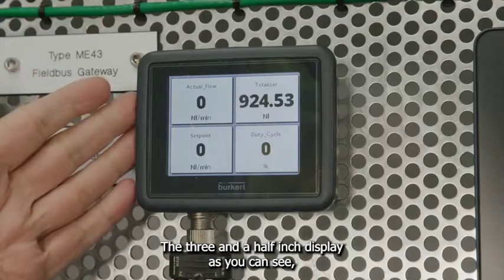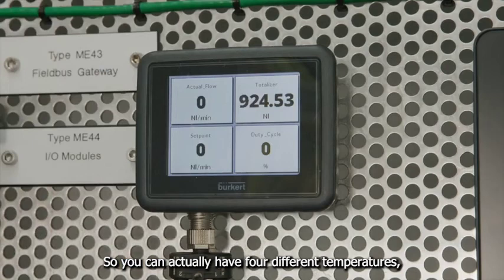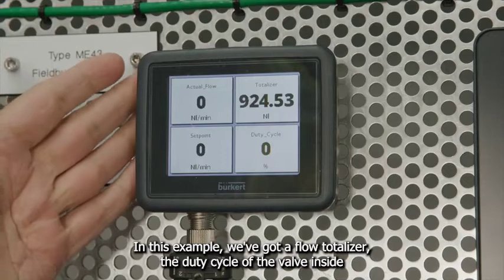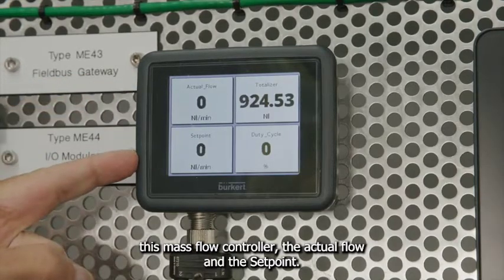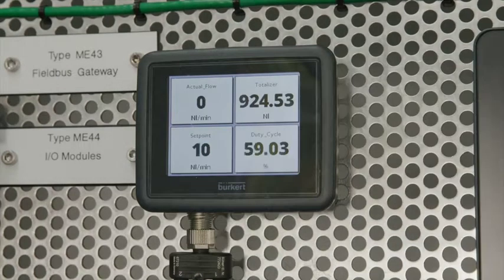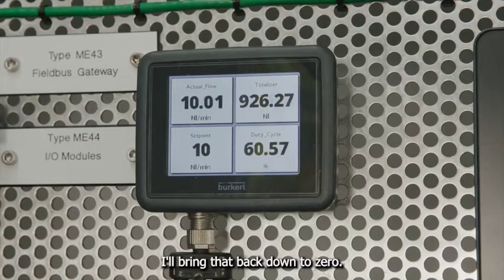The 3.5-inch display, as you can see, is a full color display and also will display up to 4 parameters. So you can actually have 4 different temperatures, 4 pressures, mixture of pressure, temperature, or whatever. In this example, we've got a flow totalizer, the duty cycle of the valve inside this mass flow controller, the actual flow, and the set point. In the PLC now, I'll increase the set point to 10. So there, the set point's gone up, and now we're seeing the actual flow also at 10. I'll bring that back down to 0.